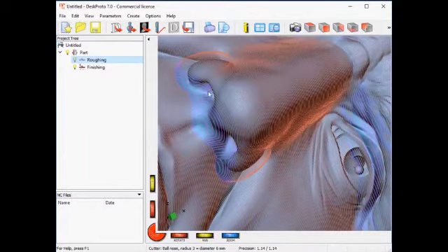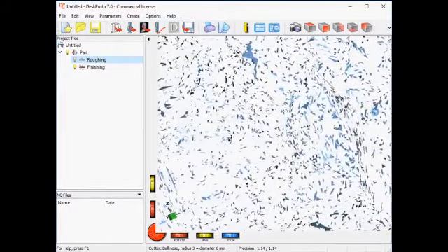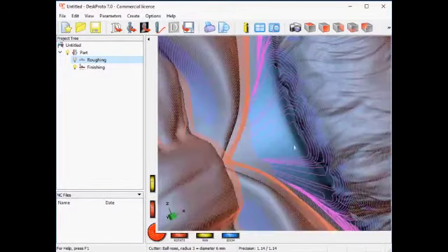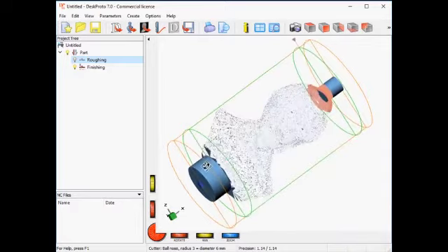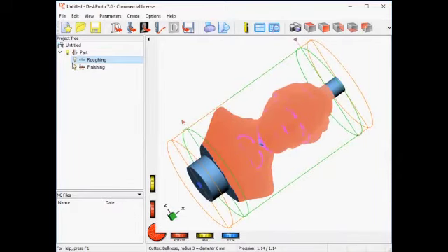Okay, for the finishing we can zoom in a bit and see many toolpaths are present. Here is an undercut. The cutter cannot reach within the nose of Mr. Lincoln. Here's a second one below the chin. However, these do not matter, as the resulting statue will be great anyway.